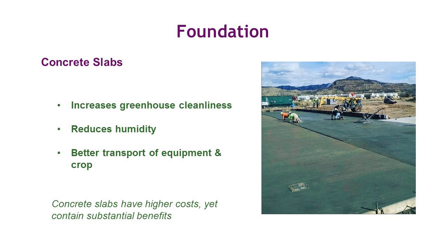However, I will say this, Dave, there are cases where concrete slabs become a challenge for the foundation. You might have to build an additional foundation outside of your floor because of high wind speeds or different reactions taking place on the column. Say you live in a very high seismic area like Southern California. Oftentimes the builder will put in a column and a caisson, but he'll still pour a slab around the caisson and for the whole floor, so you have a concrete floor. So it's a combination of both.